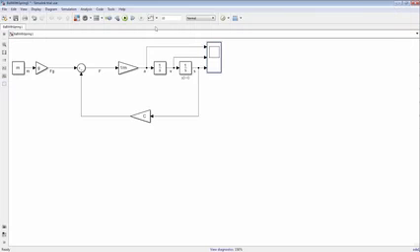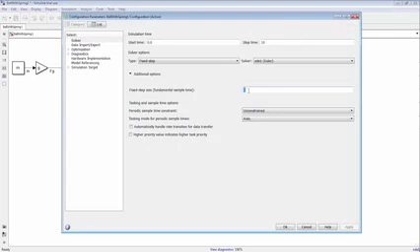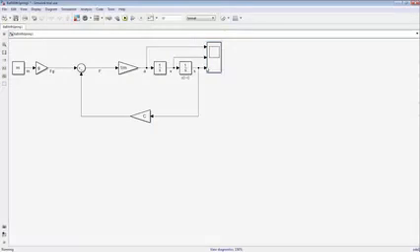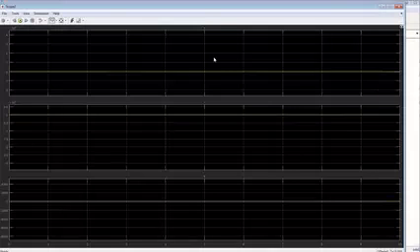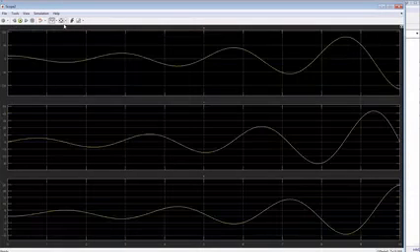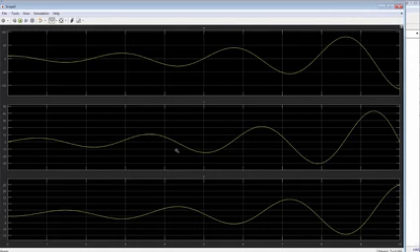So let's decrease this in the model configuration parameters, so we get smoother curves. Let's decrease it to, say, 0.1 seconds. And let's rerun it again. Let's auto-zoom. Okay, this looks very smooth, nice, but it's a bit strange. Why should our displacement grow over time? It's not as we expected.